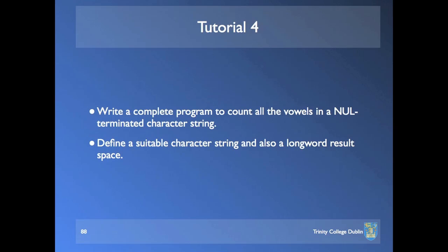And I did see in somebody's book that the condition code register is sometimes called the user byte, which is an odd name. But anyway, it's all a bit odd, I suppose. Okay, so they're the conditions. And remember, these conditions operate on the bits in the condition code register. So when they're talking there about N, it's the N bit of the CCR that we're talking about. And that MI there, minus, that condition is true if the N bit is true. PL there, plus, that condition will be true if the N bit in the condition code register is false. So that's how it works.